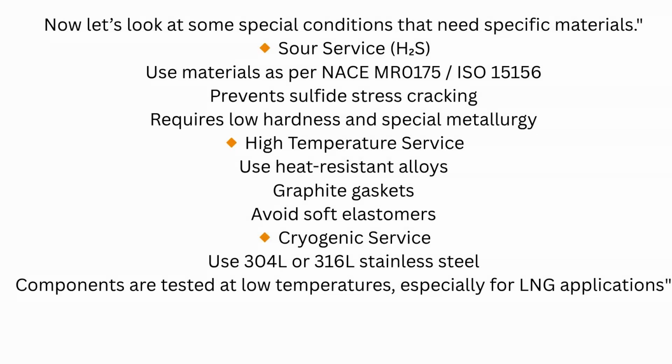Now let's look at some special conditions that need specific materials. Sour service: use materials as per NACE MR0175, ISO 15156. Prevents sulfide stress cracking. H2S requires low hardness and special metallurgy. High temperature service: use heat-resistant alloys and graphite gaskets. Avoid soft elastomers. Cryogenic service: use 304L or 316L.